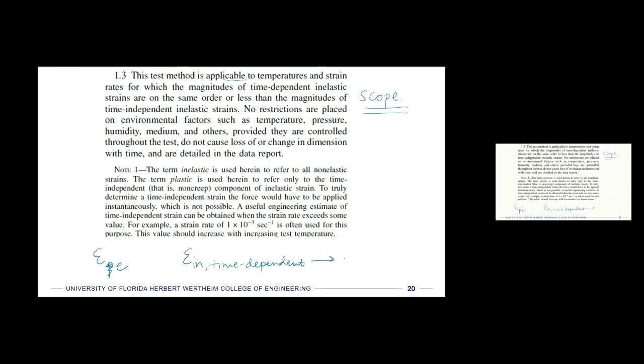So this is something we haven't yet covered in the class, but we will talk about, which is creep behavior, right? So if we have creep, everything is time dependent, right? Because creep is related to things like time and temperature. And then we also have a strain which is inelastic, which is time independent. So it basically is plastic deformation, right? A load-induced or temperature-induced change that really is not due to duration, okay?